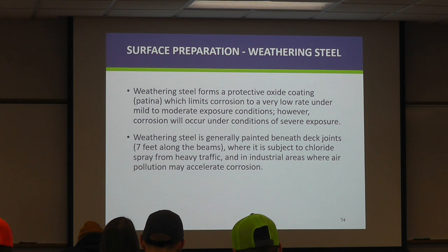So if you end up having to test for chloride as well, those are good spots to check. Directly below a bridge joint in the deck, at either end, over a pier, whatever have you. Or directly over an interstate lane, because you get a lot of salt spray. So if you need to find a place where you think that might be a good spot to check, that would be one.